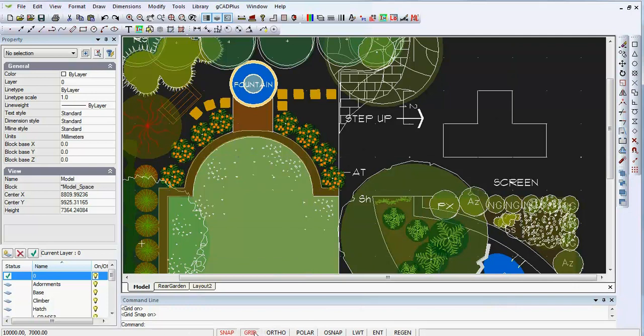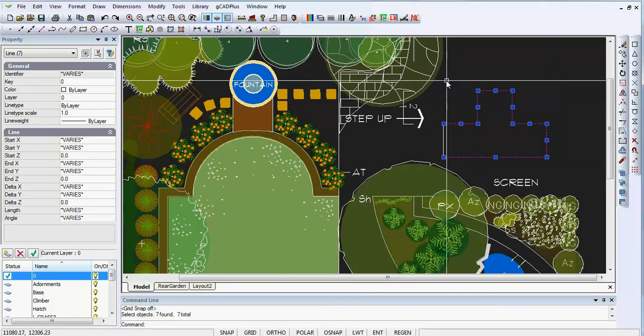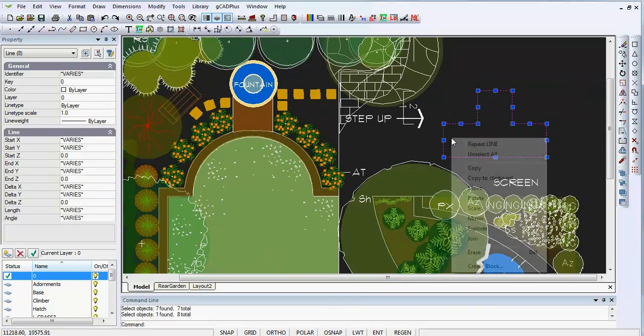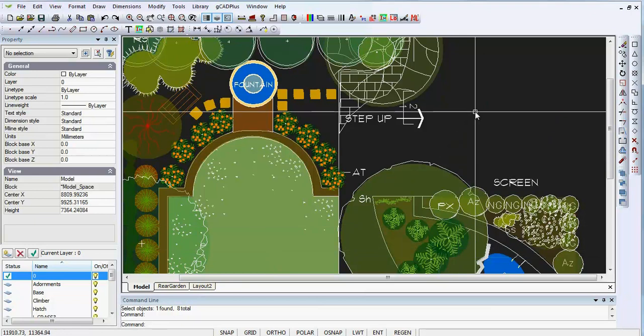You'll notice if you let the cursor hover over them, you can use function keys. Function key F7 will turn the grid off. So if I press F7 now, the grid goes and the tab returns to a black tab. F9 takes snap off. So now we're back to the normal situation. One more, right click and erase. So I don't think you necessarily have to work and experiment with things on the tab settings at this stage, but you do need to be aware of them.